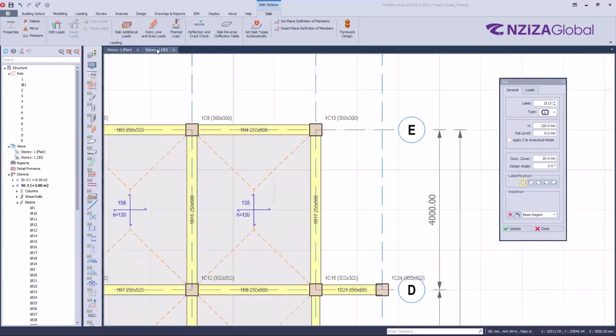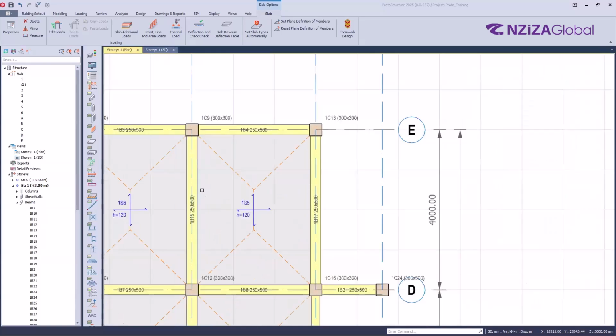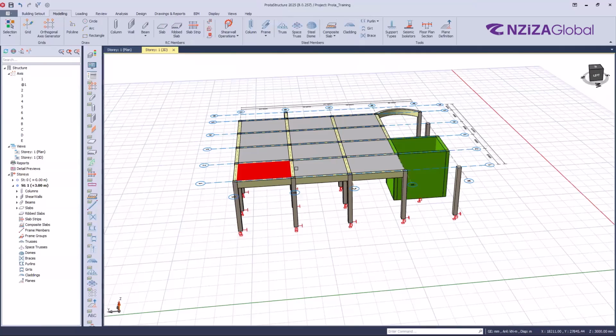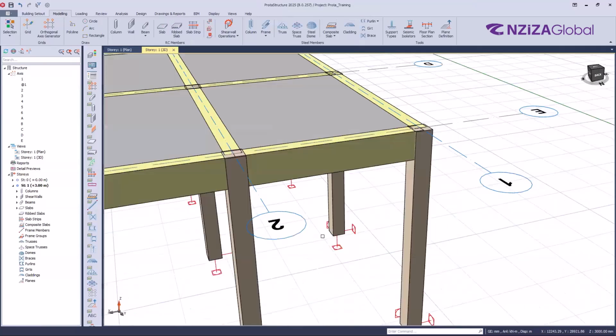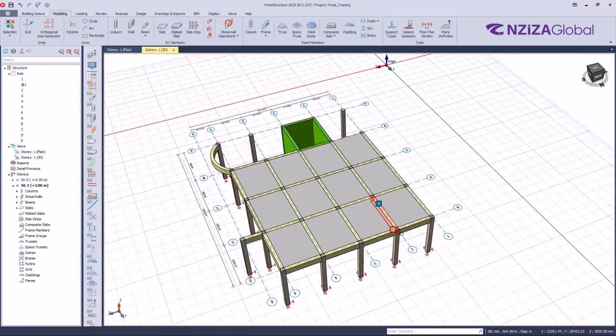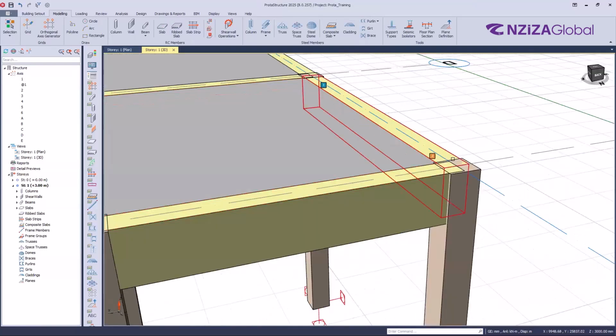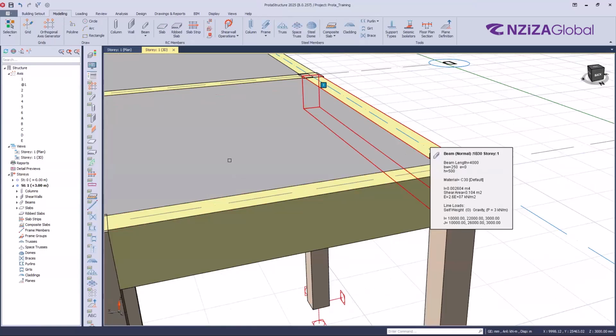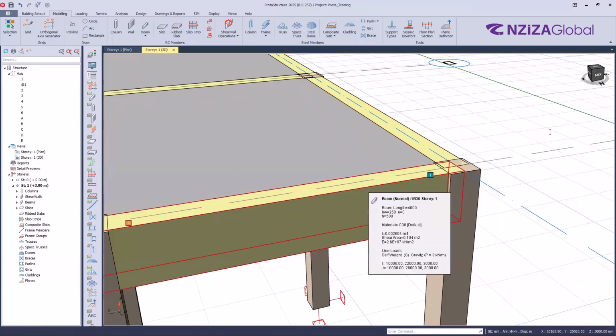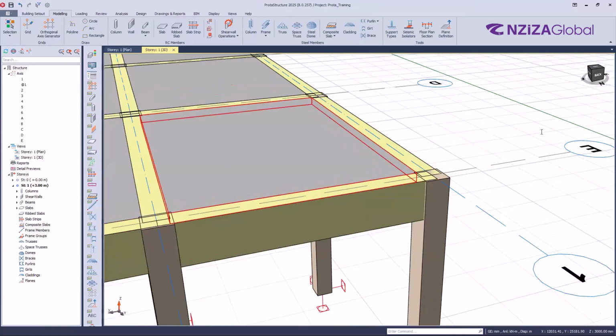So using the 3D. Okay. So if I open my 3D, okay, don't bother yourself with placing slab. We'll give you time to place slab after explaining everything. Okay. So by default, that's how the slab should look like. It is flashing with the beams and column, okay, at the top. That's because under the reference level, it is 0, okay.